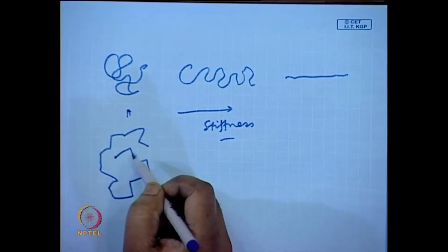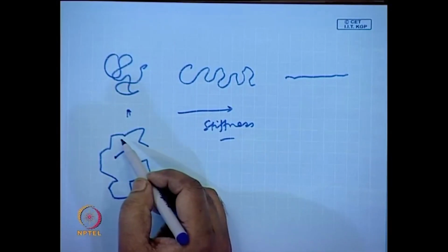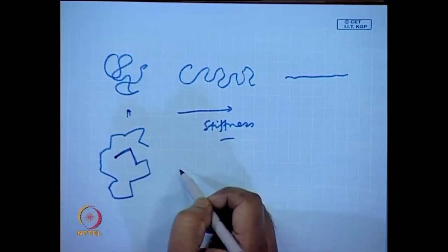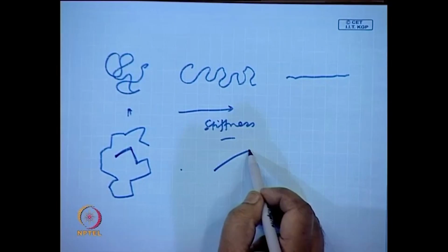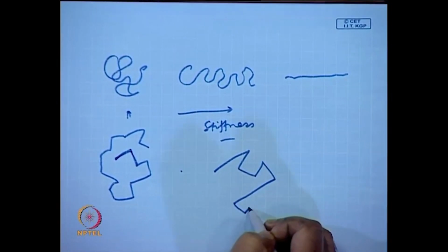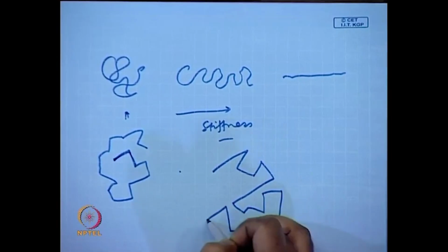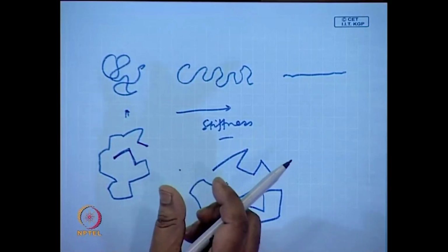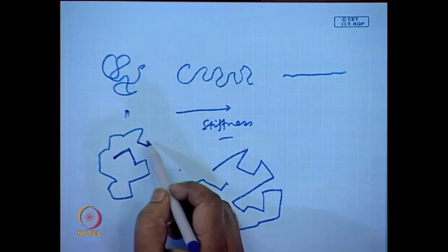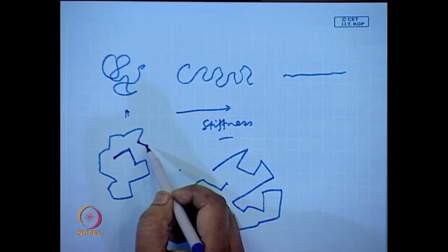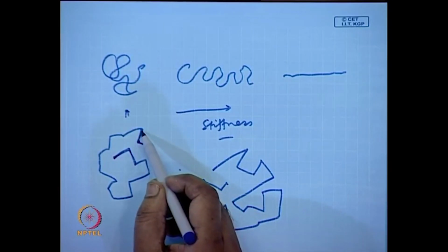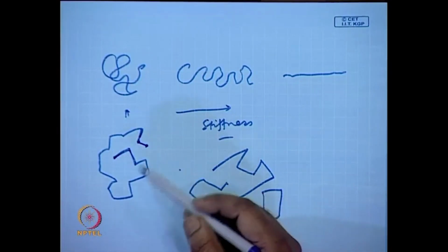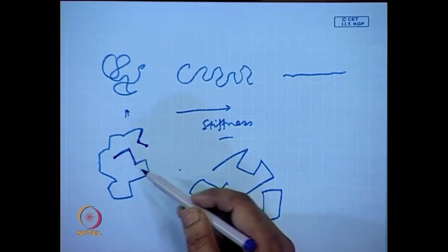Now, polymer segments or polymer bonds cannot be so random, because you have the restriction of bond length. A gas molecule can take any step it wants in any direction, but in a polymer molecule, steps are fixed as the bond length of the backbone repeating unit, and there are restrictions of fixed bond angle and also restrictions on rotation. We will come and talk about those in detail.